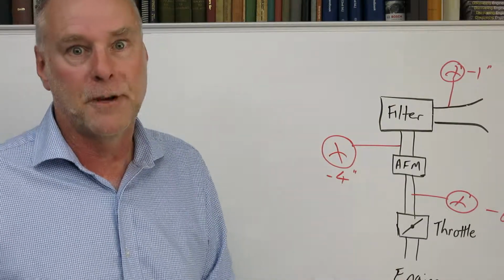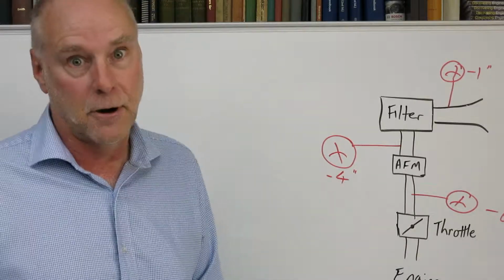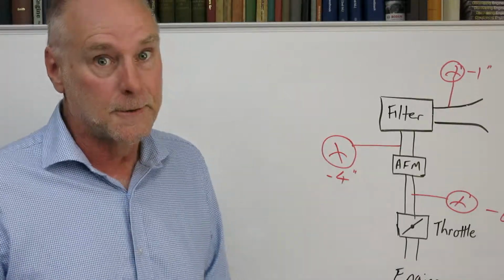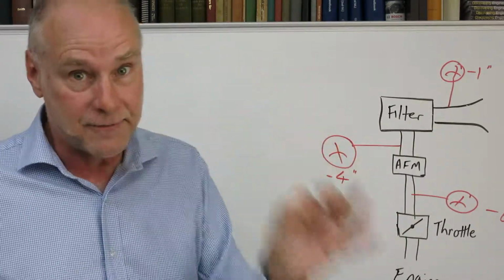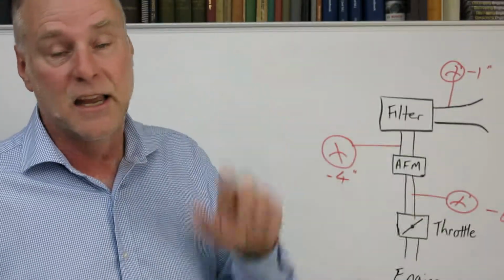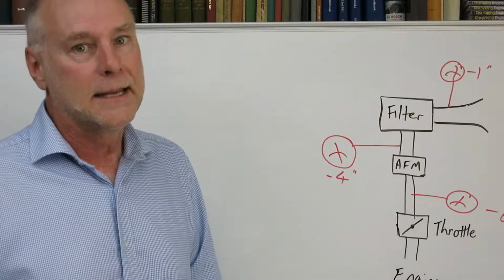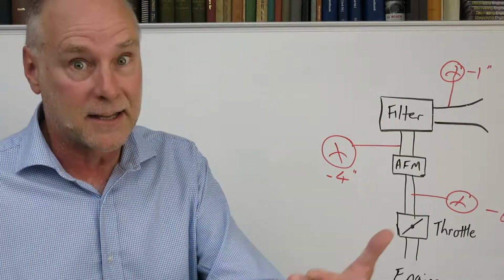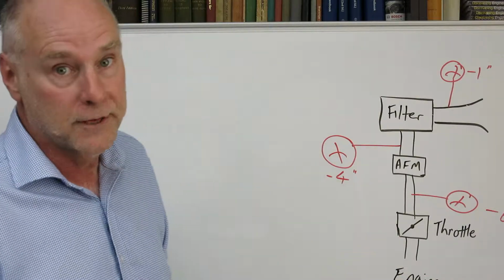That's 10% of the pressure drop in a good system and maybe only 3% of the pressure drop in a system that's not so good. Changing the filter might be easy, but in the real world of actually measuring flow, it typically makes an irrelevant difference. And the danger of not filtering the air going into your engine, as the standard factory filter does, I think is not worth the risk.